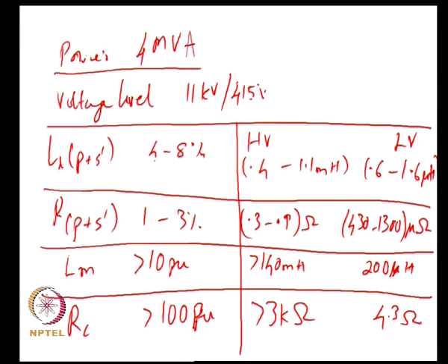So, if you say that the resistance is 1%, then you might say okay, that might be a reasonable value. If someone says the resistance is 10%, you would immediately realize that maybe it is not reasonable, it is too large for the winding. So, again the value in percentage gives you a better gut feel of what to expect in the system rather than the physical units.